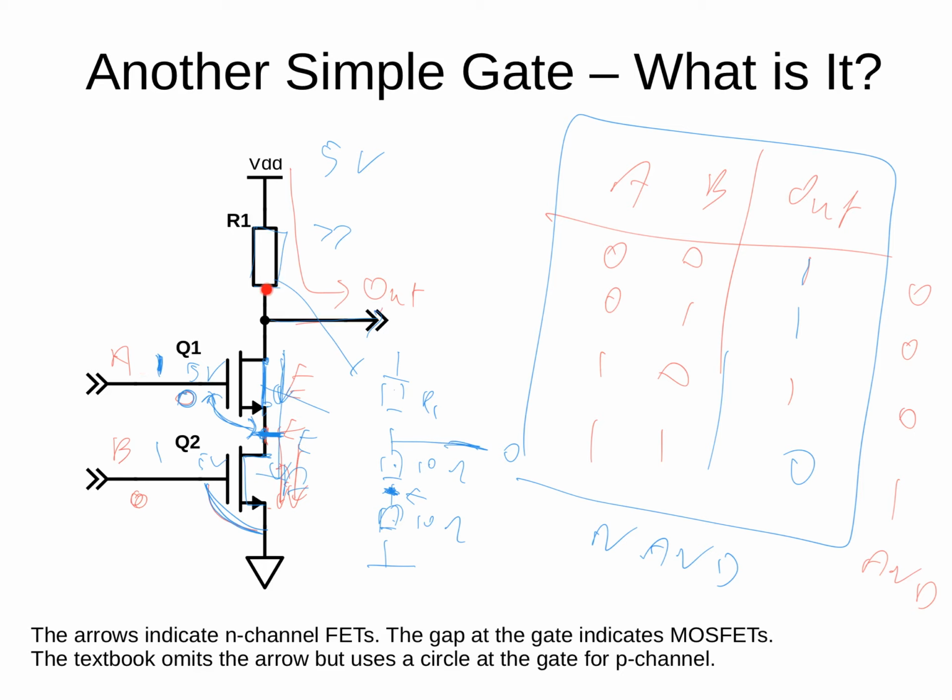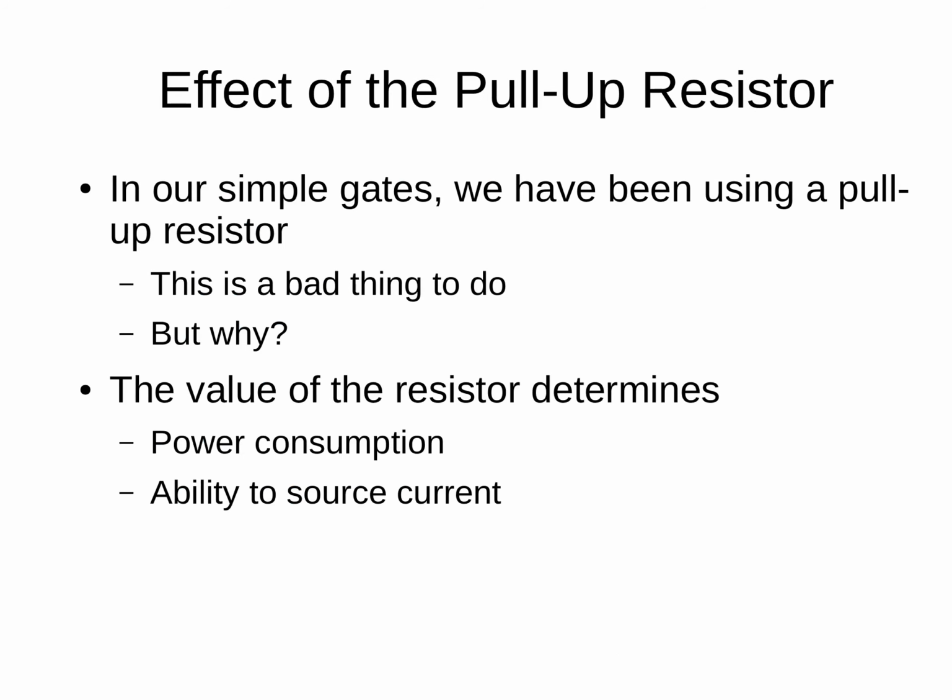Of course, we wouldn't actually use a resistor up here, but in principle we see how, using FETs, we can build digital circuits. As I've repeatedly said, using resistors is bad. It's called a pull-up resistor because we see how when our FET is off, it's that resistor that pulls the voltage up to 5 volts, giving us a logic 1 at the output.